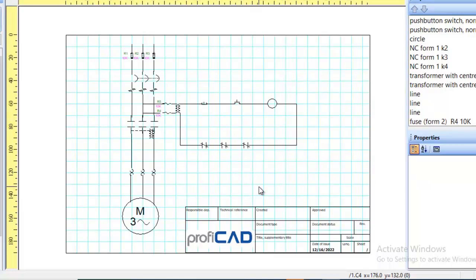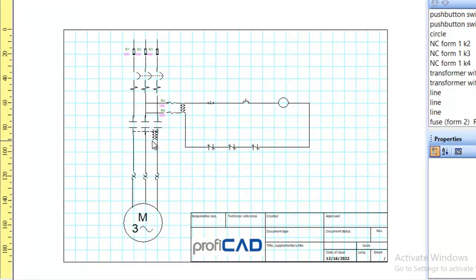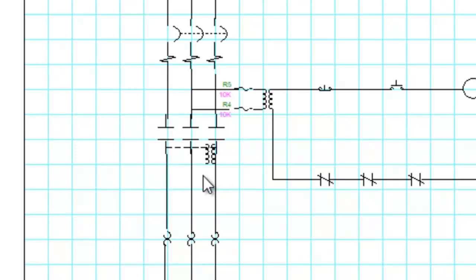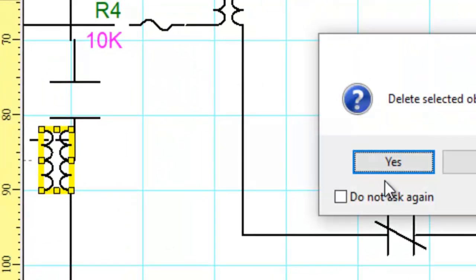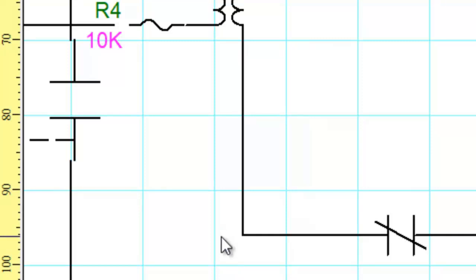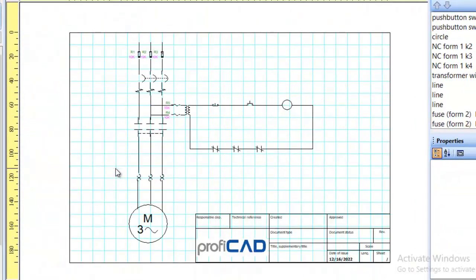So this is a very simple electric motor circuit. Okay, so you see that this is the incoming to your circuit breaker through your fuses to your circuit breaker that is magnetically operated, then to your contactor, then okay, let's see something here. That's not supposed to be. Let me expand to see what. Okay, let's remove it. Is a transformer. Okay, so we now relate it back to the 50. Okay, so now this is your contactor, and then through your overloads to your electric motor.